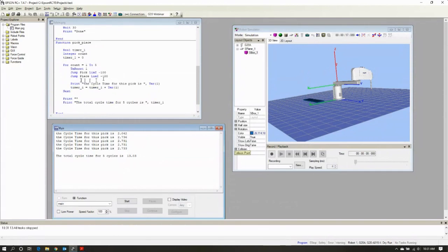Let's also say that in addition to limiting the Z stroke, we can also begin moving horizontally and vertically at the same time. It's known as the arch command. The arch command is denoted between the LIMZ and the jump with the letter C, and I'm going to say C1. So I'm using arch number 1. Well, what is arch number 1?